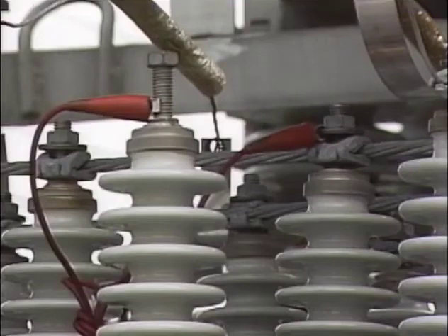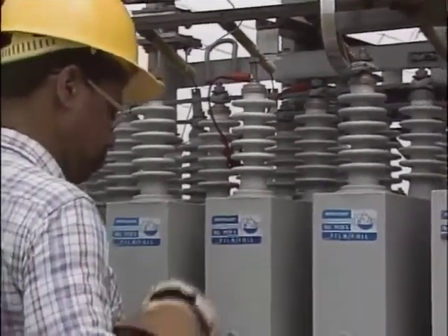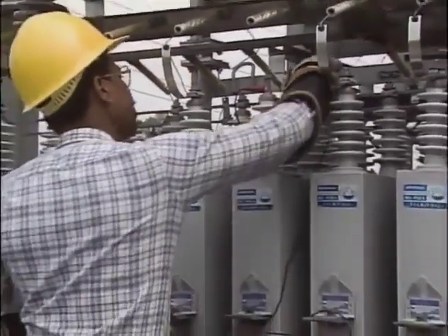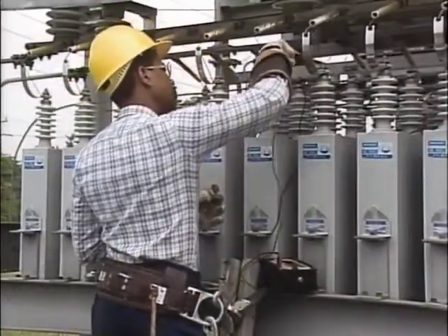For this test, only one terminal of the capacitor needs to be disconnected from the bank. It can be either terminal. Here, the normally hot terminal has been disconnected. The terminals have been shorted for safety. One lead of a handheld or portable capacitance checker is connected to the neutral terminal of the capacitor first. Then the other lead is connected to the normally hot terminal.